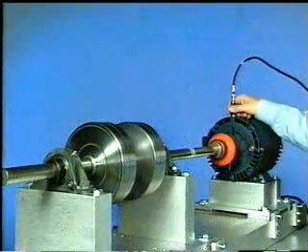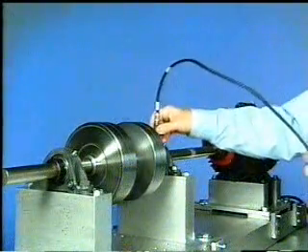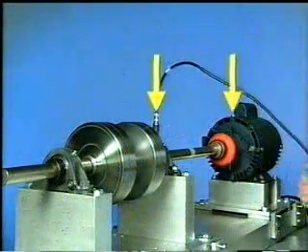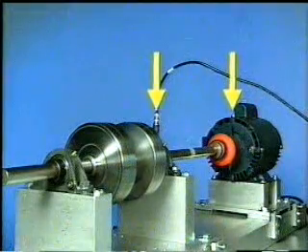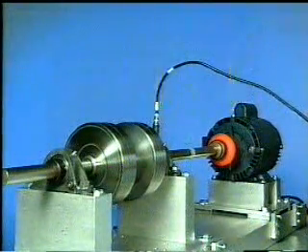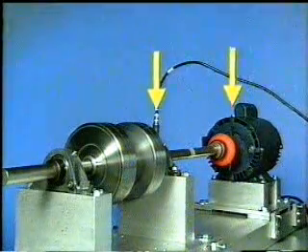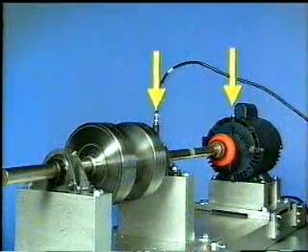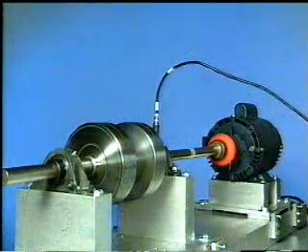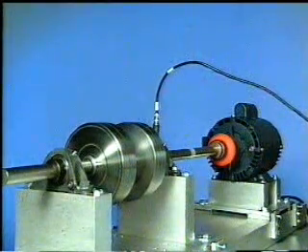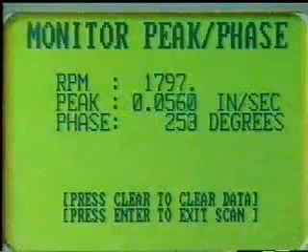For example, when we measure the phase on a machine in a vertical direction across the coupling, if the phase is about the same, then the machine is moving together. But if the phase readings are about 180 degrees out, it indicates a misalignment condition. More examples and rules of thumb are shown in the section Static Phase and Machinery Conditions.